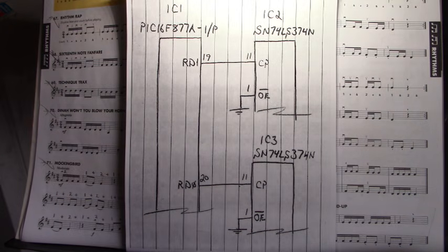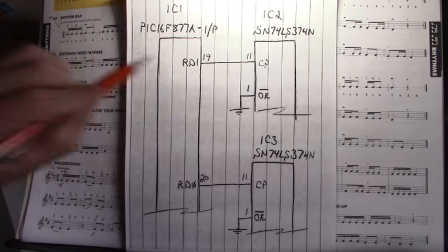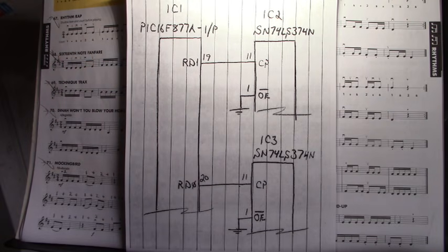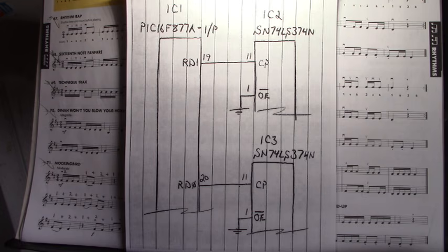Now the question presented to us is, how do we apply that data bus, the PIC16F877A I/O data bus, to the output, either the P5 connector or the P6 connector, the Hall effect output or the incremental output. So previously we saw that we could apply a Hall effect pattern or an incremental encoder pattern to the data bus, the inputs of these two ICs right here. So how do we determine whether we're going to apply Hall effect pattern data to the output or incremental encoder data pattern to the output?